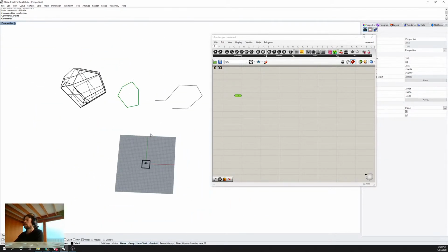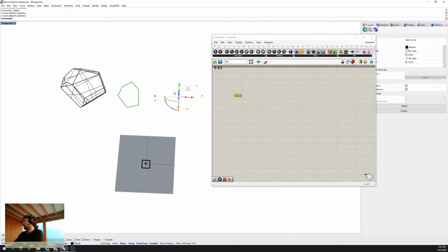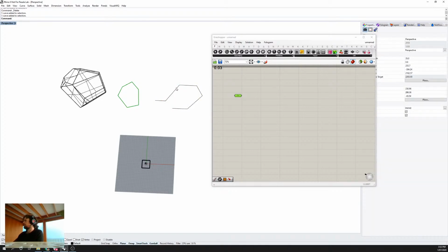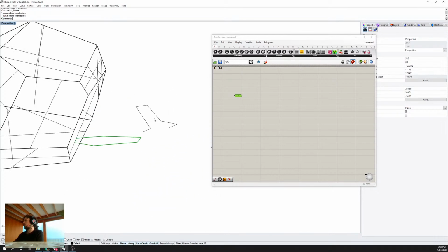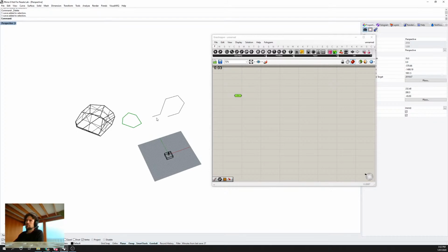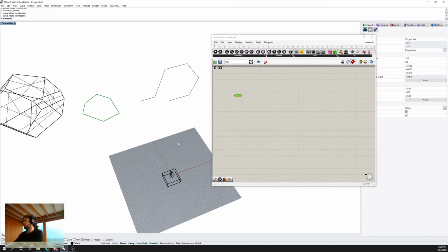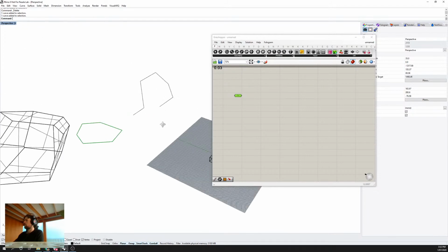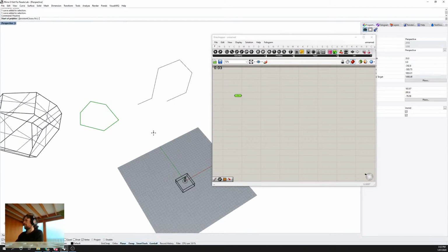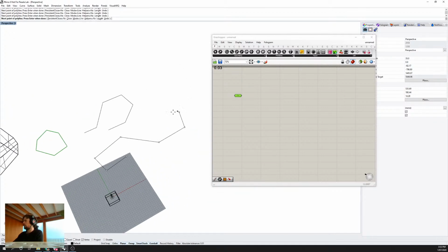So now let's have a crack at rebuilding this same tool parametrically. And we'll just do it with one part to begin with. So we're going to use this curve here. So if you're following along, just draw a polyline. Make sure the polyline is roughly 1 meter long, and you're working in millimeters. And if you want, that polyline can be in 3D. Your polyline can really look however you want.